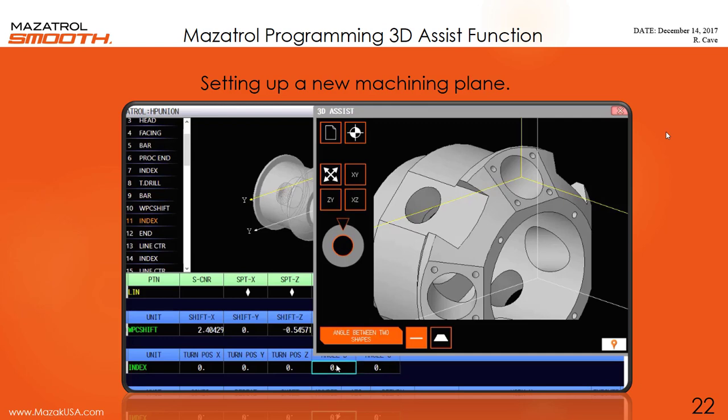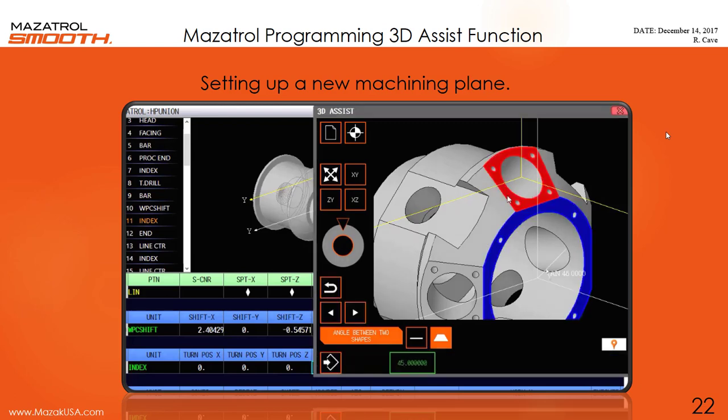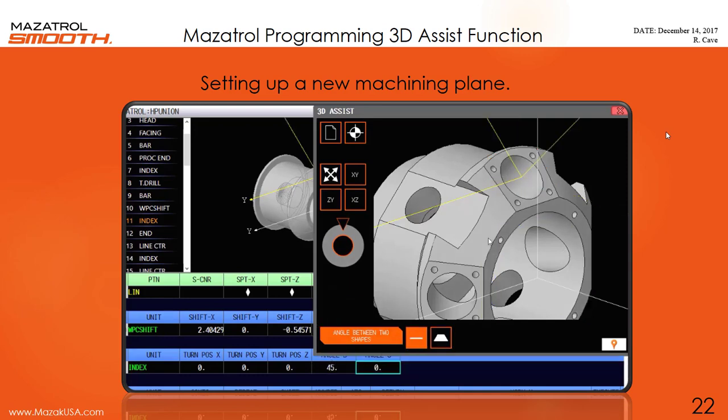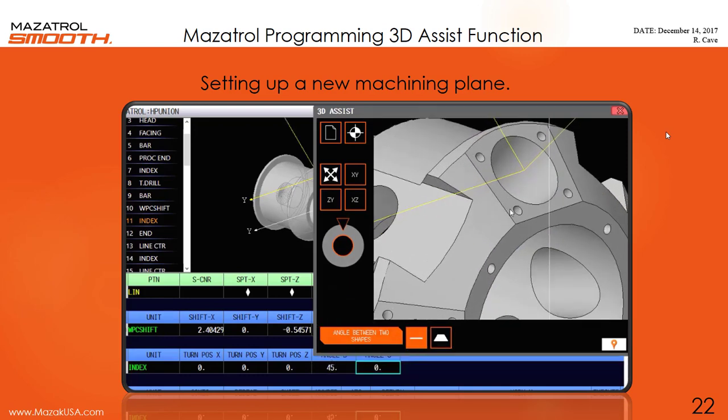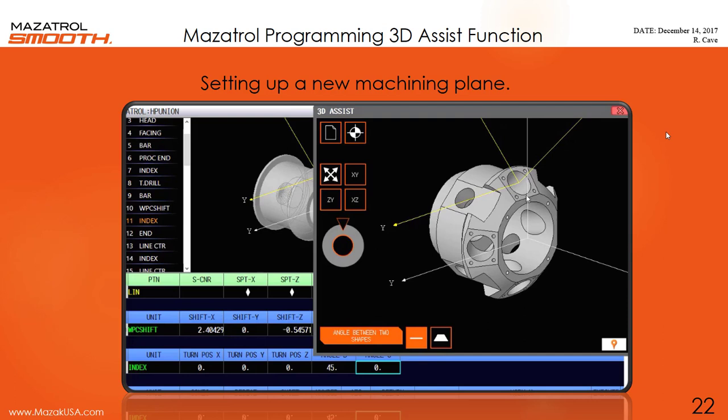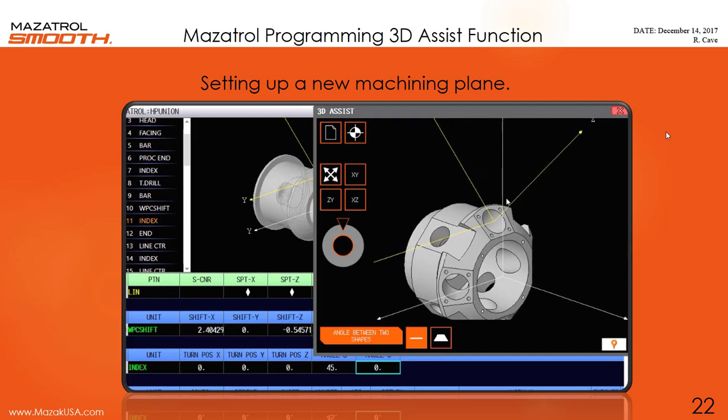I position my cursor on the B rotation of the index unit, go to angle between 2 shapes, pick up the surfaces, click on those 2 surfaces, it tells me the angle to rotate to, and just like that I've created a new plane out here on that outside flat at 45 degrees.